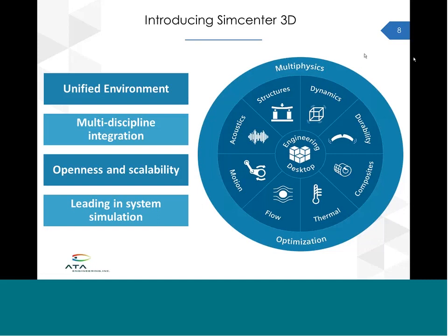And so all of these different simulation tools are now being exposed to you through the common interface formerly known as NX CAE. And by virtue of doing that, all of these disciplines can be integrated in a very user-friendly way. And at the same time, because NX is a very open and scalable environment, if you have models that were written in a format appropriate for a different solver, that can be imported into Simcenter 3D. It can be exported from Simcenter 3D, so you can still use it as a pre-post tool, even if you do want to use a different solver to actually do the solving.